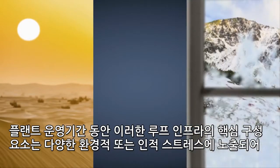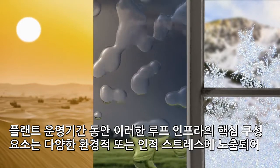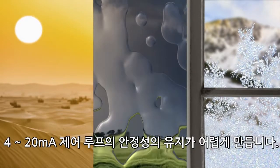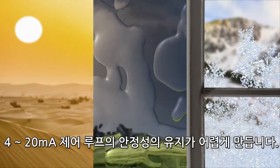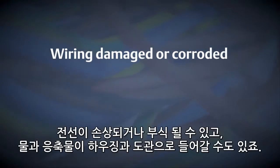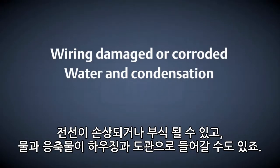Over the life of your plant, these critical components of your loop infrastructure are subjected to a variety of environmental and human stresses that can put the reliability of your 4 to 20 milliamp control loop at risk. What are some of these risks? Wires can become damaged or corroded. Water and condensation can find its way into housings and conduit.